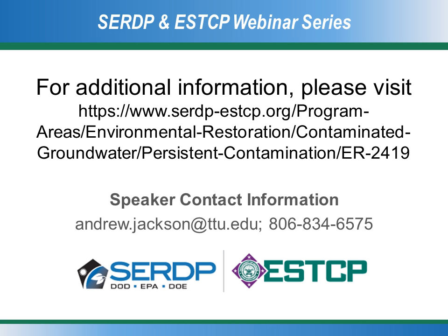Yeah, it could. That's exactly the issue with using it in a kind of a hard rock environment, is that you want to make sure the sample cells are querying the domain directly outside of them and not getting vertical flow. So as long as you could develop a system in which you're sure you've prevented vertical flow, then they could definitely be used in a drilled borehole type situation. That would be similar to other passive technologies that have been used in similar situations.